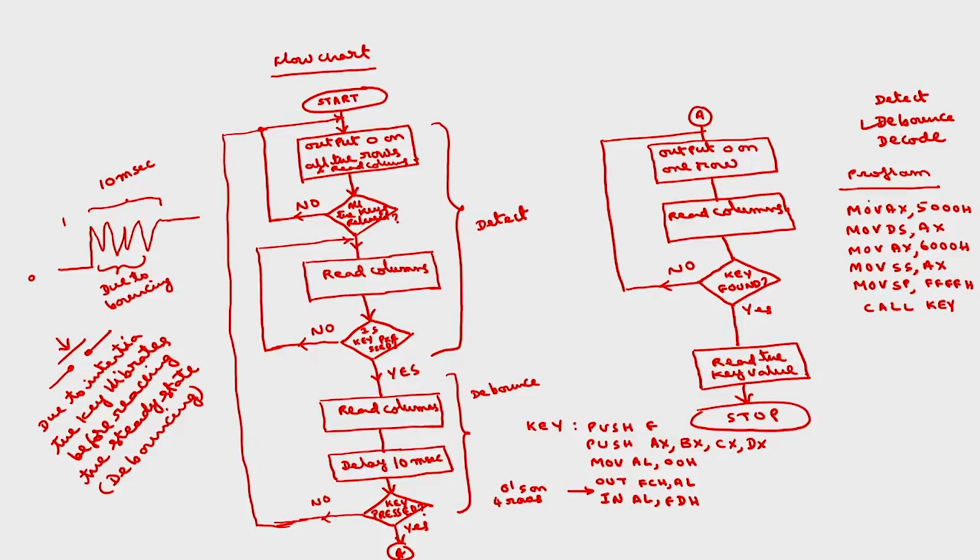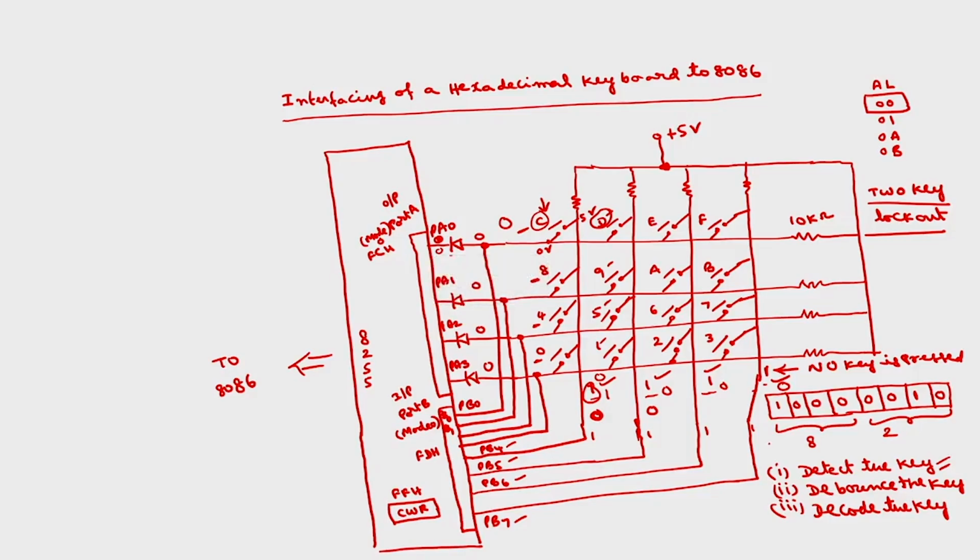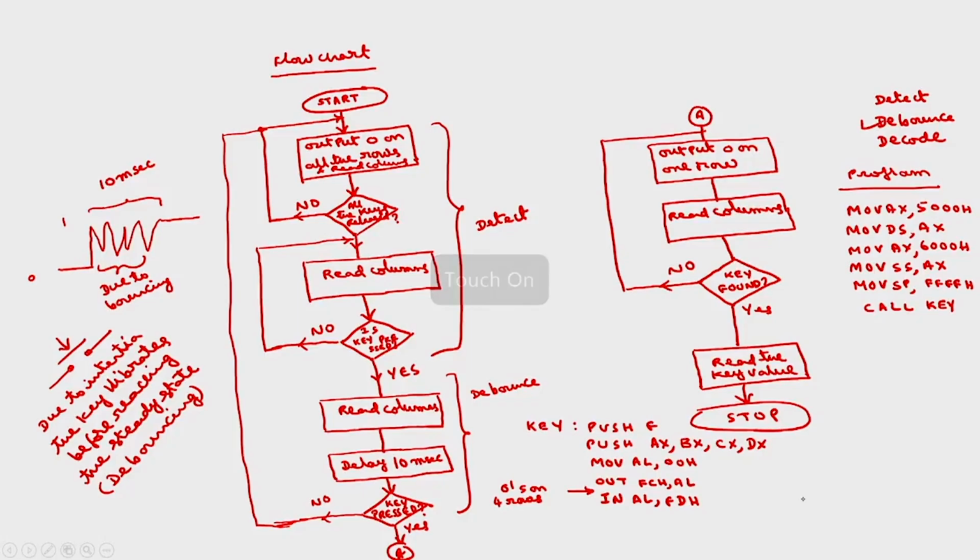So the very first instruction in this program, I have forgotten. You have to initialize the ports. As I have computed, this control load register I have obtained as 82H. This you have to take into control load register. You can write it here also. So the first 2 instructions are move AL comma 82H, out FF comma AL. So this will program port A as output port and port B as input port in mode 0. Because this is just initialization only.